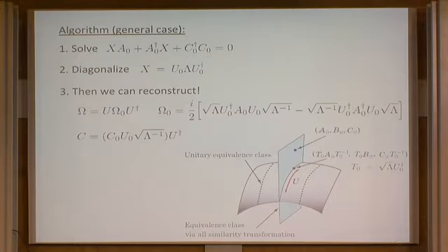So just before we go on to that, I guess another approach that would come to mind to solve this problem would be, we know that these passive systems have this all-pass property, the lossless bounded real property that Guofeng talked about yesterday. And so then what you can do, and I think that's in the paper by Nina and myself, is you can solve the lossless bounded real lemma.